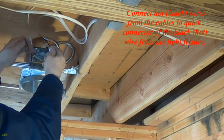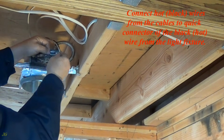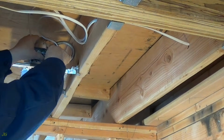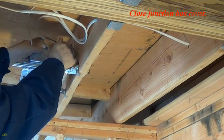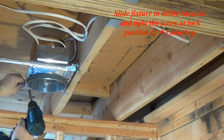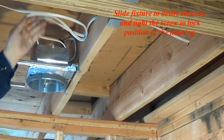Connect hot, black wires from the cables to quick connector of the black, hot wire from the light fixture. Close junction box cover. Slide fixture to desired location and tighten the screw to lock position of the housing.